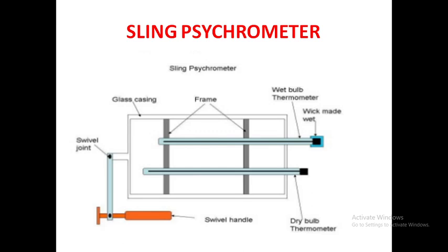Drawback of this equipment: the measured medium is disturbed due to the act of measurement. The evaporation process at the wet bulb will add moisture to the air. It cannot be used in automation requirement situations. It cannot be used for continuous recording purposes.